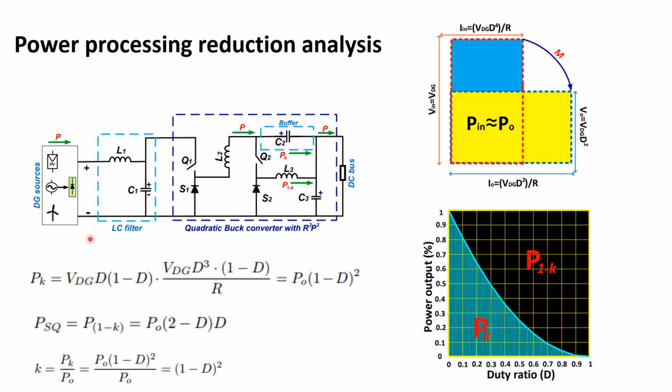The reduction of power processing to improve efficiency is one of the key concepts proposed by partial power processing for high-gain converters. This structure introduces a buffer element that processes a fraction of the power directly to the load from the second stage of the converter to the output. One of the advantages, analyzed through the area modeling as proposed in this article, is the ability to evaluate the directly processed power, which enhances the efficiency of these structures through a factor of K, examined in detail within this document.